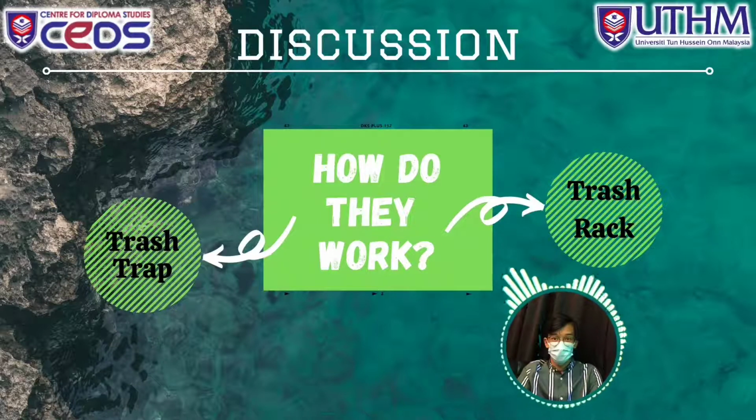When a flood occurs, trash racks are used to prevent blockage and damage to water pressure pipelines and hydropower turbine runners caused by drift, branches, leaves and debris such as dirt. To prevent energy loss, this gadget is constructed with a water velocity of roughly 0.6 meters per second.